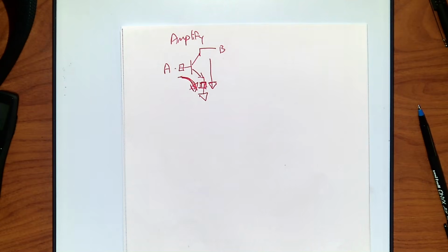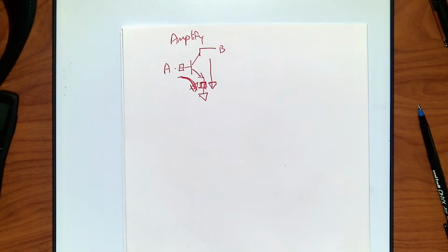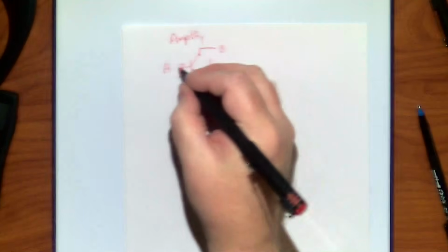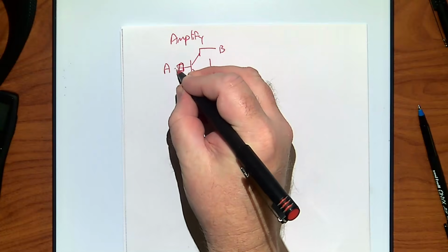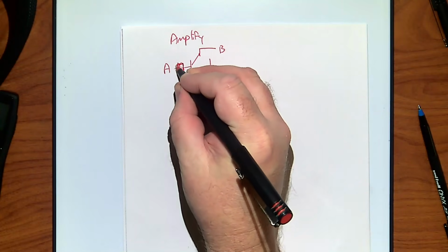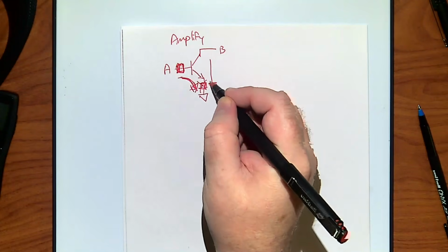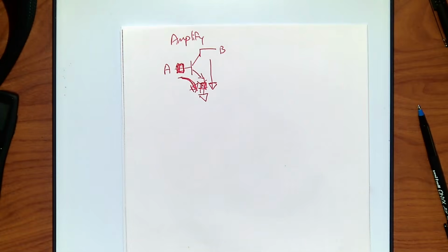I want the zero to be as low as possible, because this B is my output, not something raising my zero voltage up off the ground. So I don't want this spot. That's why you always see the resistor here, because it will protect this, but it will not cause a change on your output.